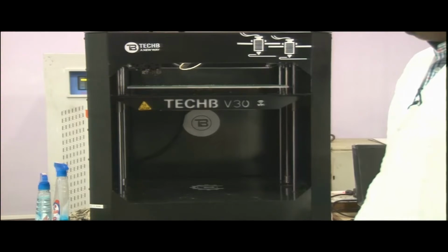The precision and smoothness of the printed models are also influenced by other factors, such as the bonding force between the layers, whether it is lower or adequate, and the weight of the upper layers that squeeze upon the lower layers. Printing problems like warping, misalignment, shrinking, and shifting of layers could all be there. And there is a difference in post-processing as well.